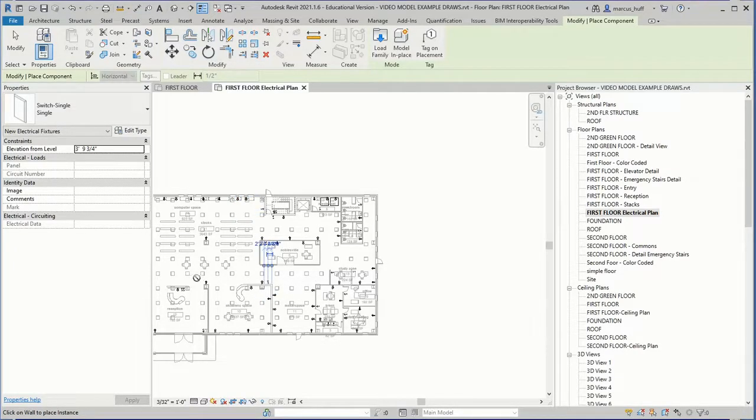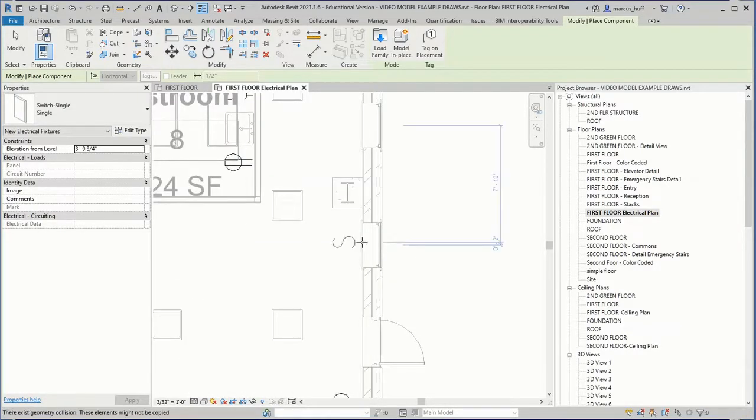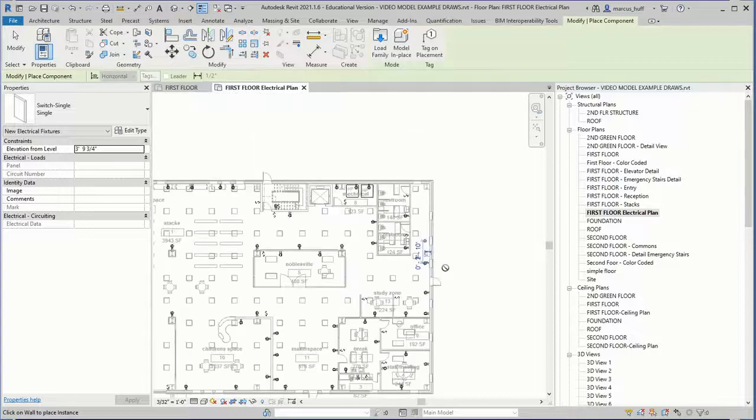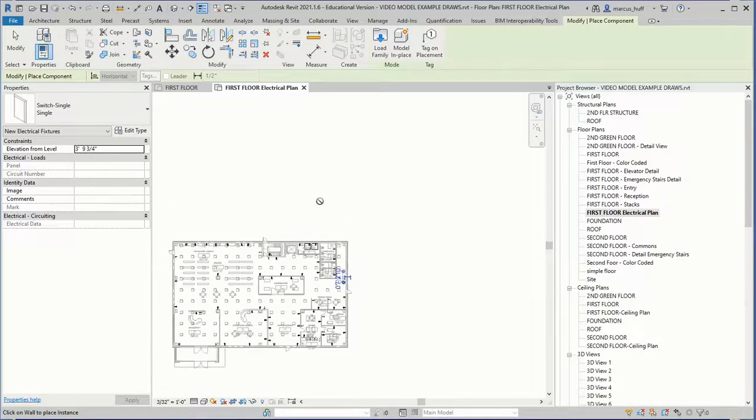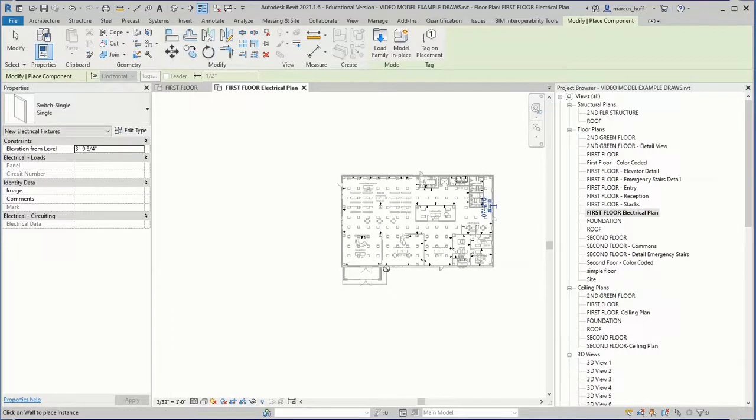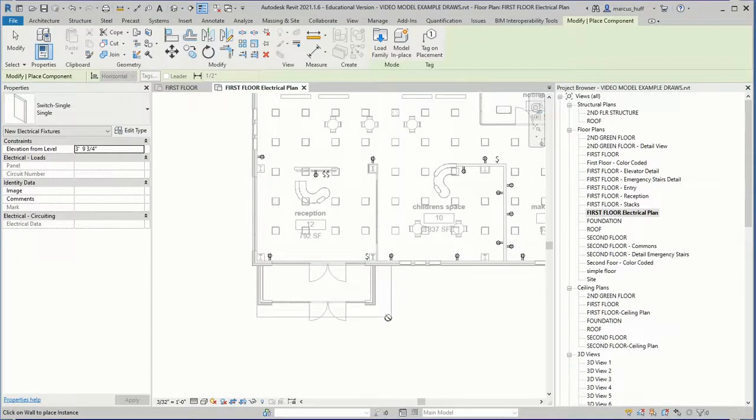You would probably have multiple switches for this interior big chunk of lights. You might have a switch here for this hallway. So just think about, as you walk around the building, where would you have switches to turn lights off and on to get around the building, okay? So once you've got that done, we've got a nice, clean, tidy electrical plan.